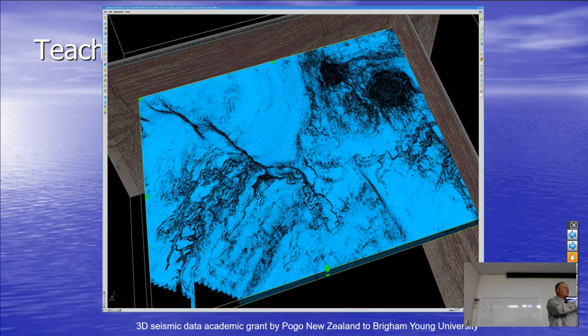So if I've got a fault, the traces are going to be different across the fault. Because if I've got layers like this and I move them down, right across here, they're going to be different. The geology is going to be different on either side of the fault. So we can pick up boundary conditions in the processing of the seismic data. Pretty simple to do. With data sets using this class, we could do it in about 2 minutes. We can come up with different attributes, and this particular attribute is trying to highlight edges in the response of your reflections.